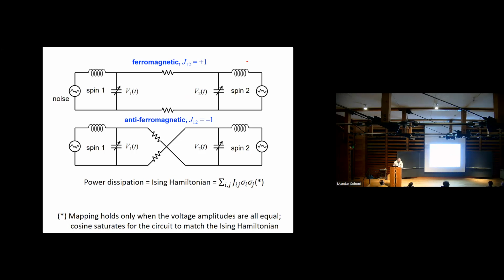You have these bistable elements. They're basically parametric oscillators where a capacitor oscillates at 2 omega, then you have gain at omega. But the gain is phase sensitive, so it locks into 0 phase shift or 180-degree phase shift. So it's bistable in that way. And then if you connect it to another one of these things, that's sort of equivalent to a magnet, but it's actually, there's nothing magnetic in it, it's just electrical. If you connect it with parallel wires,